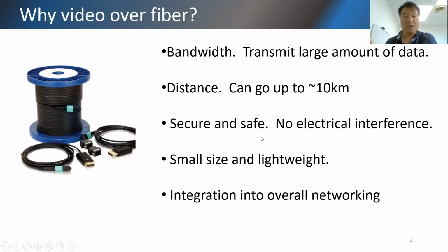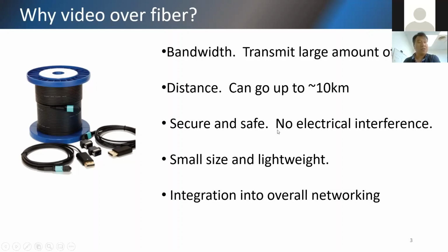As many of us know, it's almost impossible to tap into optical fiber because it's just light. So there's really no electrical interference. As you can imagine, if a customer is involved in, let's say, MRI, which uses a tremendous amount of magnetic force for the medical imaging, clearly you don't want any electrical interference, any electric field around it. So in that case, it's not even about distance. It's just physically, or by technology requirement, they need to have optical fiber.